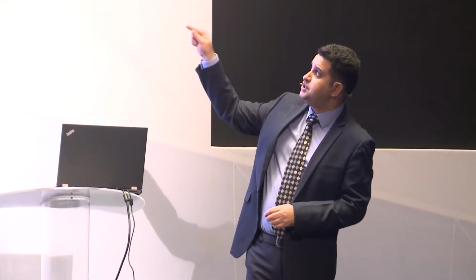Just in case you have an old style of total station, which are manual ones, I can feed this CSV file, and it will find all the hanger locations for me. Now, actually, this tool which I used here, we call it point layout. You can even use the points for walls, doors, windows, slabs, or any architecture element, any structure element. But I just use a specific example here with the structure, MEP hangers. But it doesn't stop you from adding these points on any other devices or any other systems in the project.